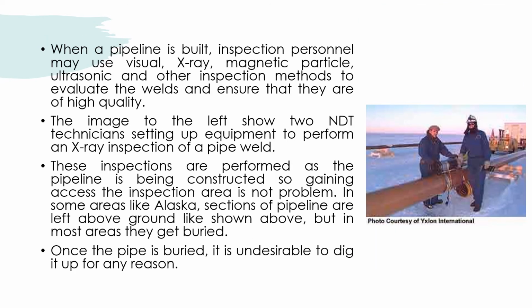When a pipeline is built, inspection personnel may use visual, X-ray, magnetic particle, ultrasonic, and other inspection methods to evaluate the weld and ensure that they are of high quality. When pipelines are built, they are made as individual pieces and welded together to make a huge pipeline